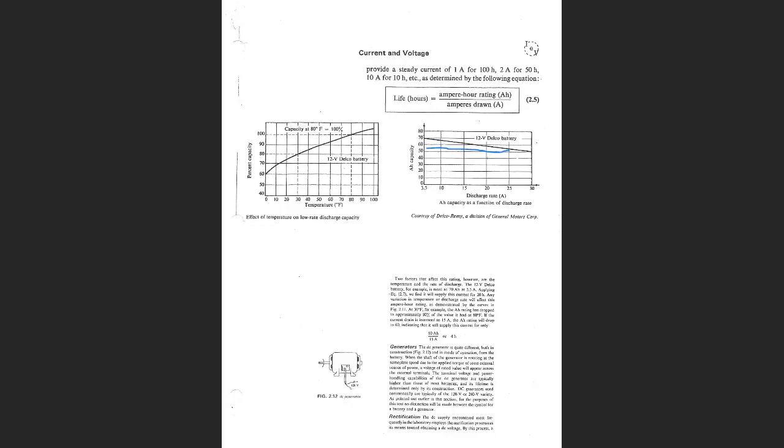So what that's saying is, in this equation right here, ideally you would write 70 amp hours for that battery. Well, that depends on how much current you're drawing. You can use a 70 if you're down here at 3.5 amps or less. If you're up here at 25 amps, if the circuit you're hooking up to that battery is drawing 25 amps, then you've got to put in the top of that equation something like 55.